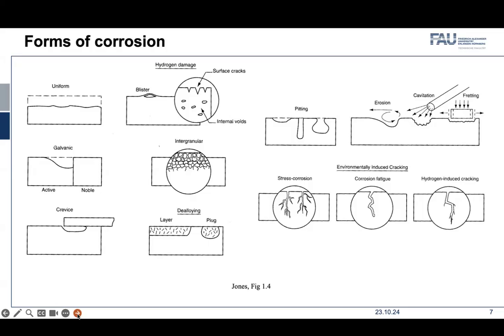And sometimes there is another form of localized corrosion: crevice corrosion. When you have rivets, like if you screw a metal screw over another material, you create a small gap where the electrolyte can move in, but it gets trapped there. There is a stagnation, and as dissolution takes place, the metal becomes much more concentrated, and it continues to attack locally under this crevice. This is a stagnated region.